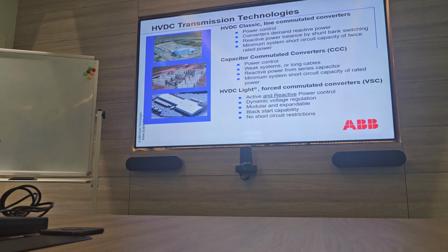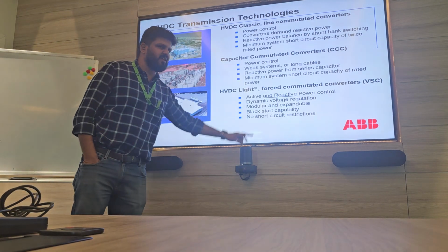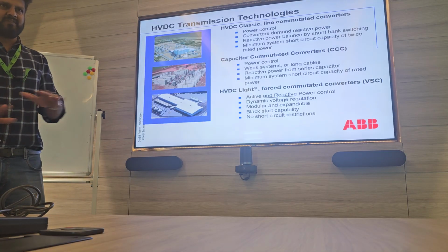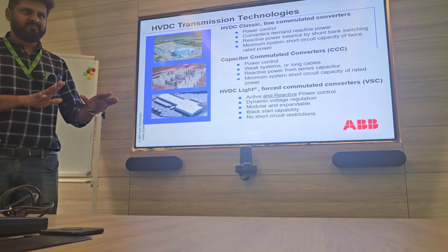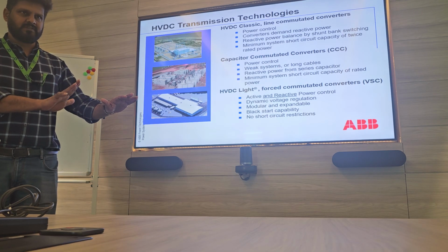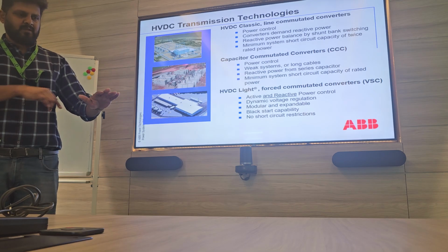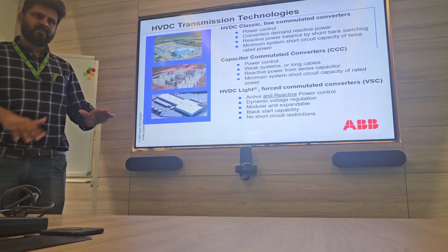Black start? Black start capability. Black start means if one network is out, with completely no power due to some major issues, for example on one side, the right side, the other converter station will feed power, but this side, the converter station, is completely blacked out.